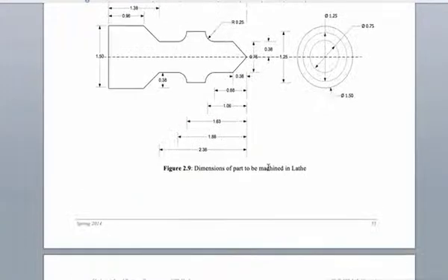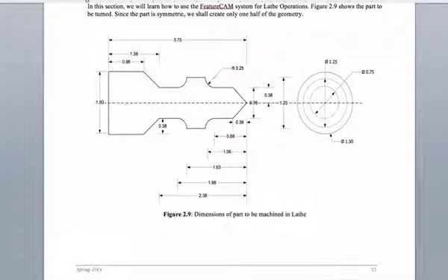The design is actually here. As you can see, it's symmetric with respect to its axis, and in this engineering drawing, we have a full specification of the contour for the workpiece. If you think about what we are doing in FeatureCAM or the G-codes, we are guiding the tool to go along this curve or contour. So in FeatureCAM, it's not necessary to draw both the upper part and the lower part, because the workpiece is turning. Once you draw the upper part, the lower part will get machined automatically, right?